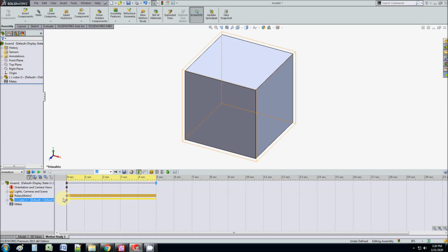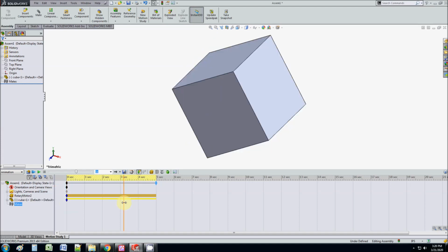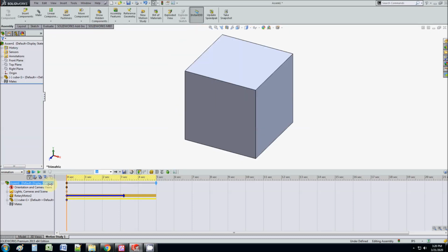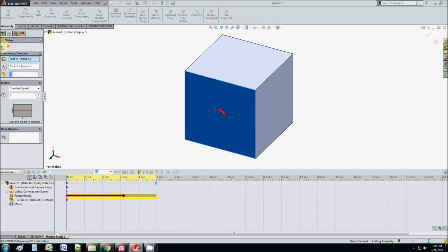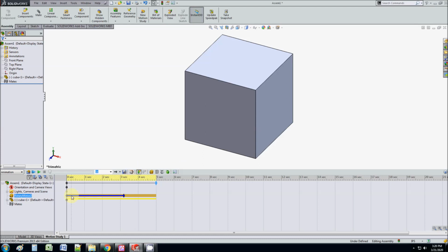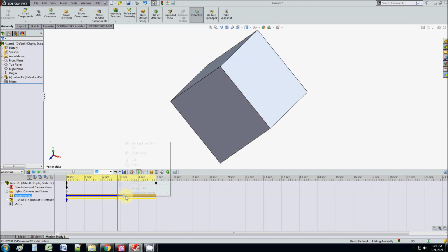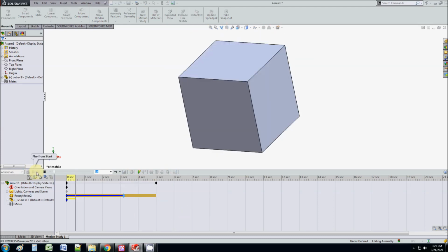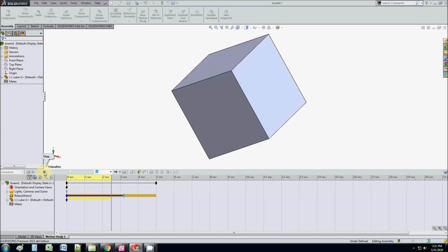And let's say you wanted to go from 0 to 100 RPM. Well, guess what? You gotta go here, edit feature, change this number. Let's say to 200 RPM. And then you go back to the beginning, hit properties, edit feature, and then hit 0. So because we have auto key on, it's gonna go from 0 to 200. And you can even add an ease in, ease out interpolation. So let's see if we recalculate. See how it's going faster and faster?